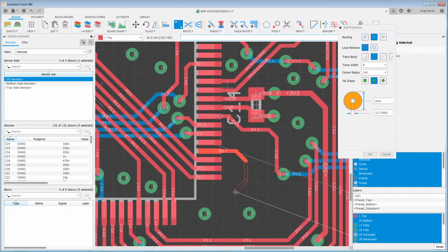There are many reasons for this, mostly aesthetic. It can help avoid acid traps. When the board is formed, it's etched using typically ferric chloride or a similar type of acid. What happens is if you have very tight corners, in the corner bend itself you can get acid accumulation there, and it will over etch.